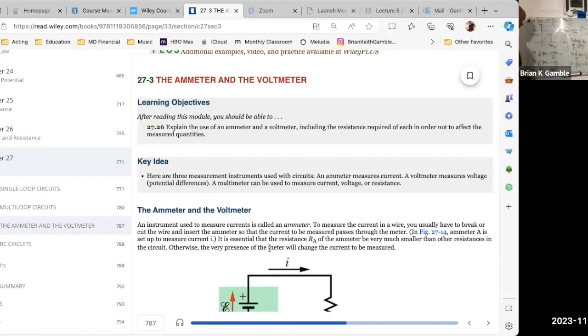I'll go ahead and finish this out because it's just simple. And then we're done, right? Because now it's separated, but here I don't have a complex type of function. So it's just going to be straight log. So for the discharging capacitor, I'm going to get minus 1 over RC times t, plus a constant. And over here, I'm just going to get log of Q of t plus a constant.